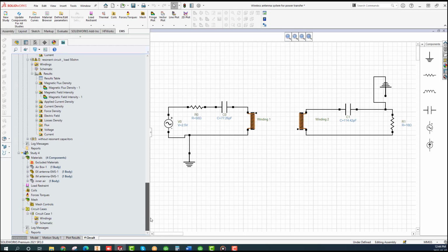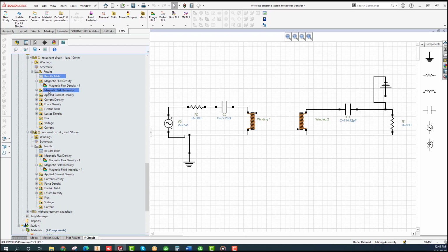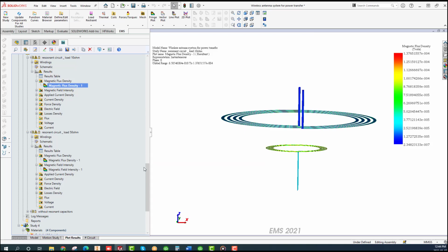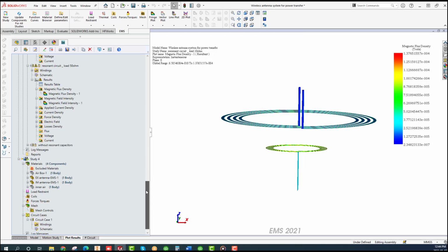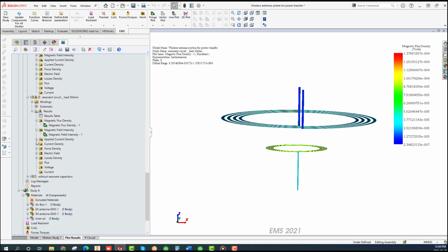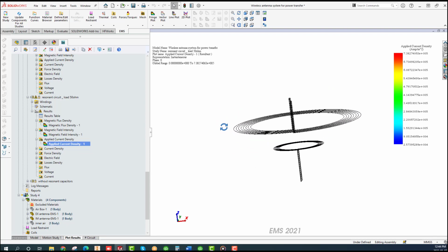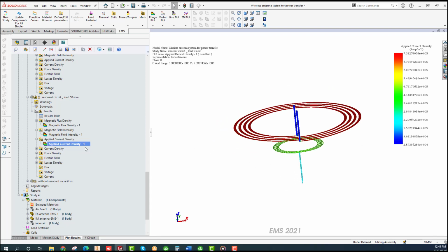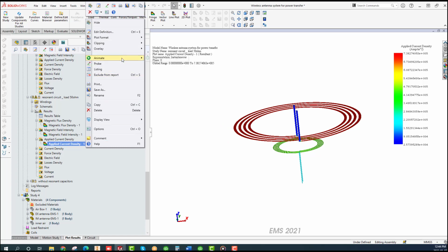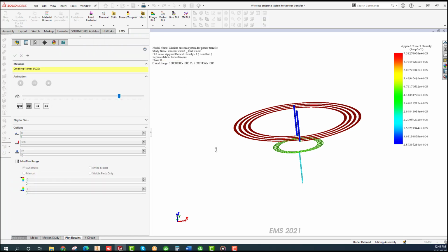To answer the question why resonant wireless power transfer is a highly efficient charging technology, as briefly explained in this webinar, the addition of the capacitor and the choice of an operating frequency equal to the resonant frequency of the circuits, the transferred power from the transmitting coil to the receiving coil is maximized. It is also less sensitive to the distance and alignment between the coils. No wonder the resonant wireless power transfer is becoming the number one power transferring technology for most emerging wireless charging devices.